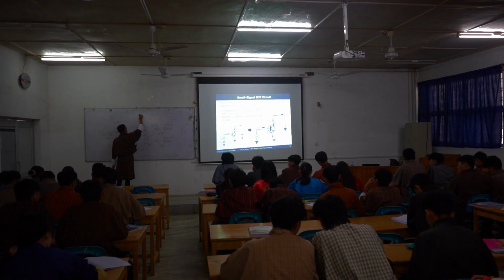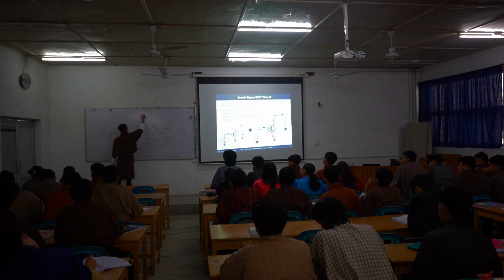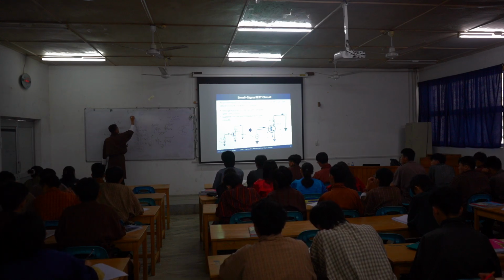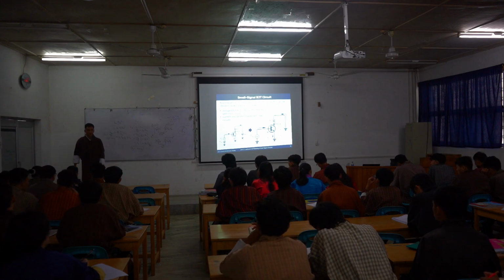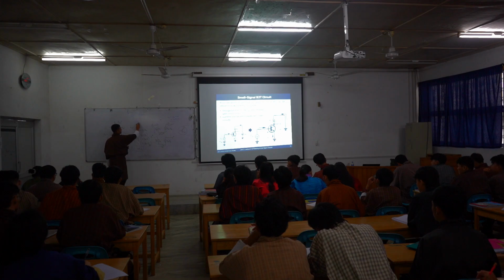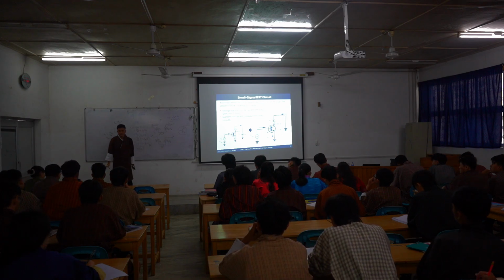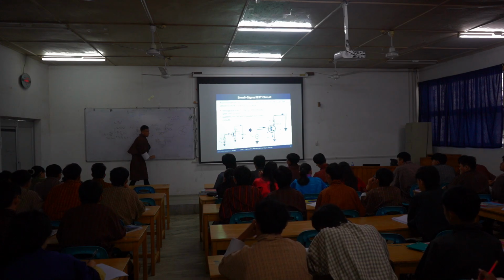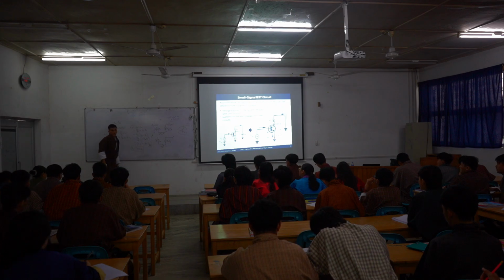So this current can also be represented with beta times IB, with R pi. Sometimes your hybrid pi model can also be represented by this. Instead of GM times VBE, I can also represent this current source with beta times IB.